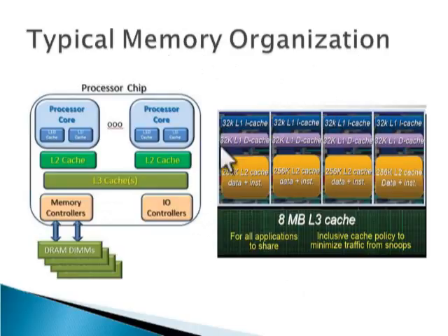In a multi-core processor system, we can have the last level cache shared between all the cores. So we can see the concept of shared cache architecture in this case also. This 8 MB L3 cache is shared between the four cores of i7 processors.